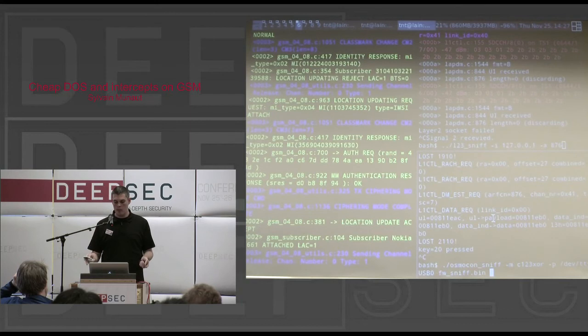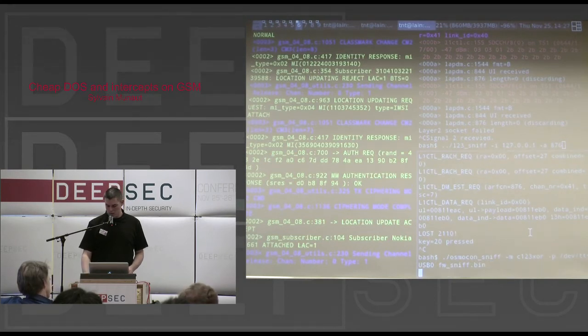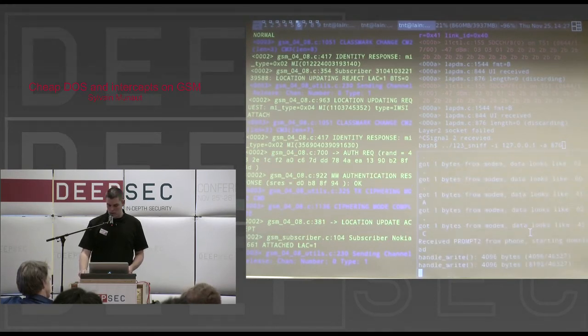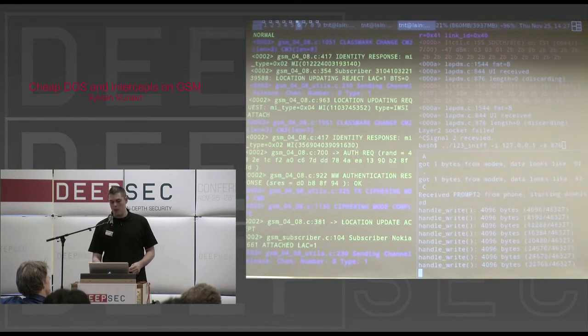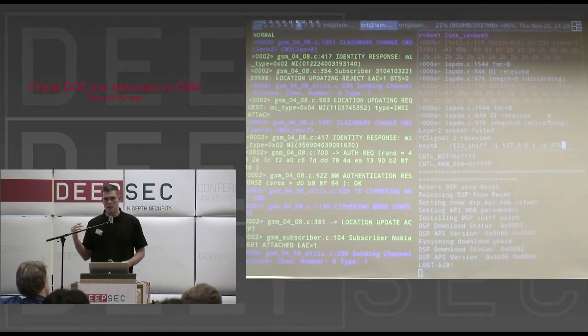And using the sniffer phone, I'm going to record the uplink and downlink of this one. Of course, I will have both sides of the conversation since I'm listening to both uplink and downlink at once. So I'm loading my modified firmware inside the phone. What the sniffer application does is it listens to the assignment channel where the GSM network tells, okay, you go to that dedicated channel, and switches to the first assignment it finds, listens to it, and up until there is nothing left to listen to.